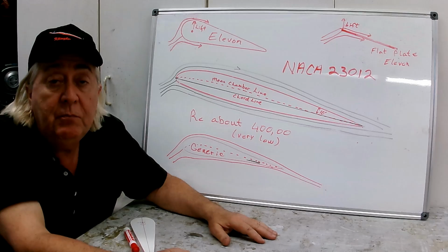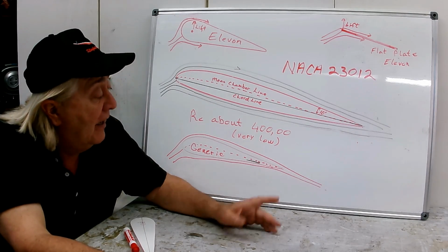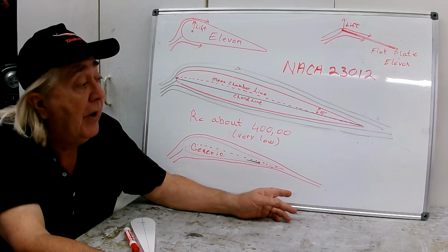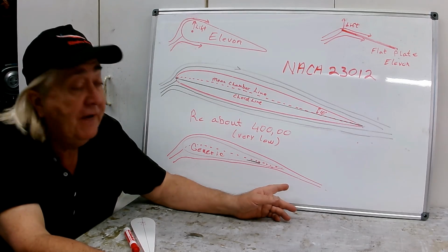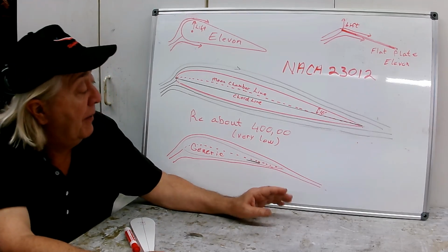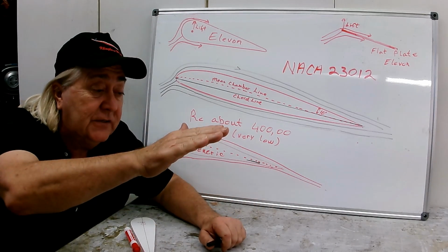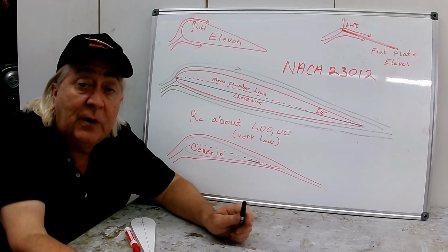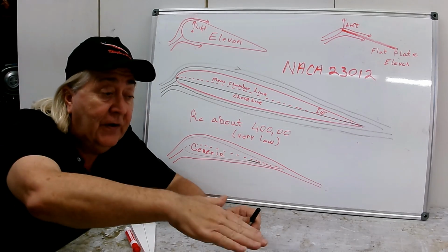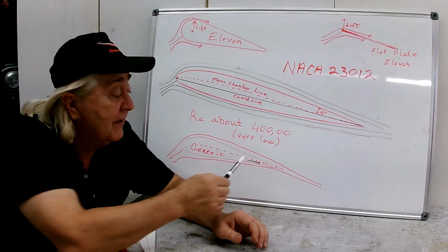You'll see that on most aircraft that fly. If you go out at the airport on a foggy day, you'll actually get to see this flow behind the wing, and it's fascinating to watch. This is typical, but for flying wings, we don't like that so much. The downwash causes the aircraft to pitch nose down. That's why we have a tail. The tail puts a down load on there and lifts the nose back up. This is all a result of generating lift.